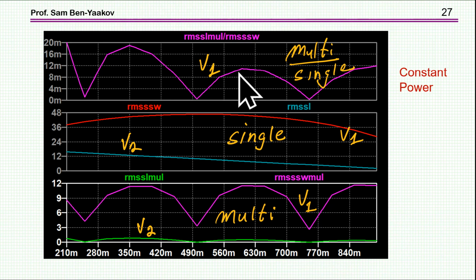So therefore, you see this difference here, but again, we are interested in the actual ripple, and this doesn't change much. Here, however, for the V2, for the output, I see some change here, okay? And so there is some difference because of the way the duty cycle is operational, but the main point here is that you have all the information here, and you can of course obtain whatever you need for your design.